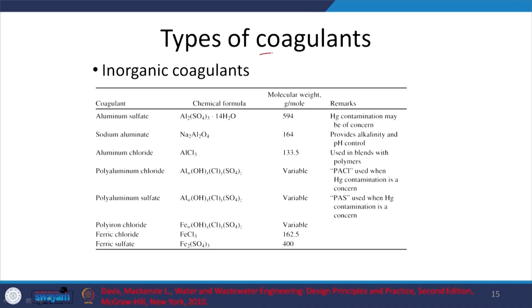What are the types of coagulants? We will look at typically addition of coagulants, such that you are going to have charge neutralization or form bridges between different particles. So, here we have two major aspects, one is charge neutralization, the other one is bridges.